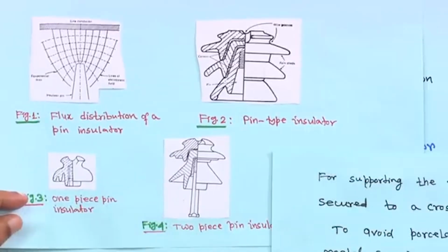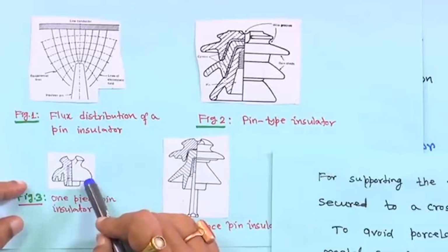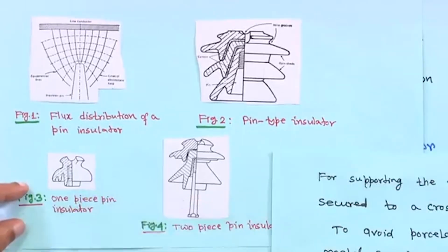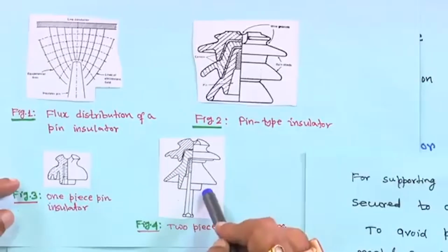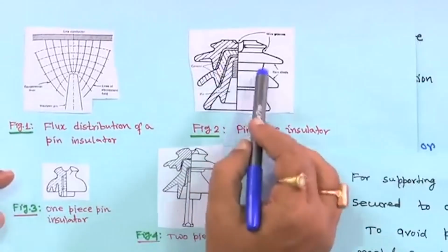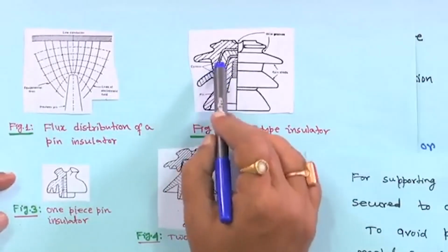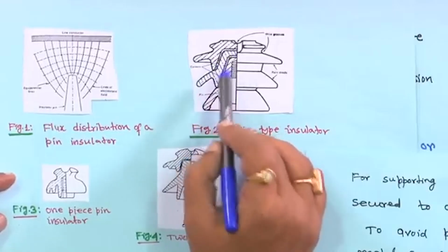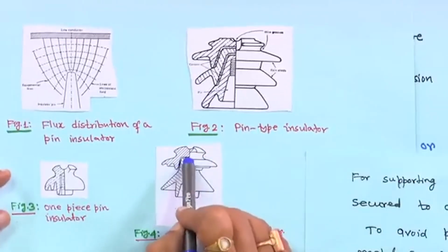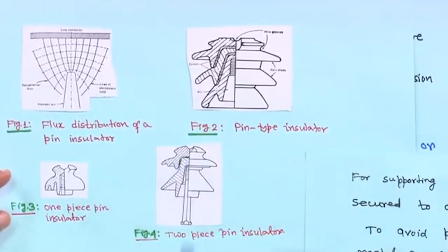Generally the thumb rule is that 1 piece means in general 11 kV, 2 piece means 22 kV, 3 piece means 33 kV, like that. This is 2 piece, but the philosophy everywhere remains the same. If it is 3 piece, you will see two cemented coverages here, but if it is single, sorry, 2 piece, then only one cemented thing is there, right.